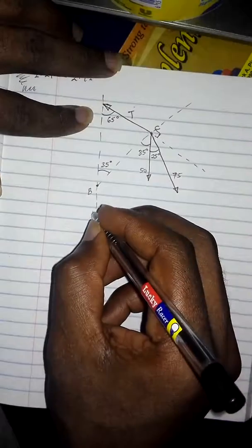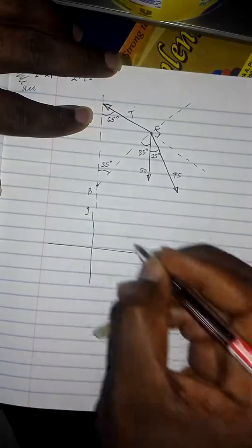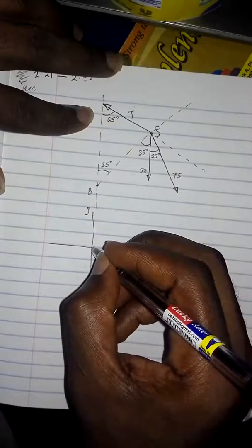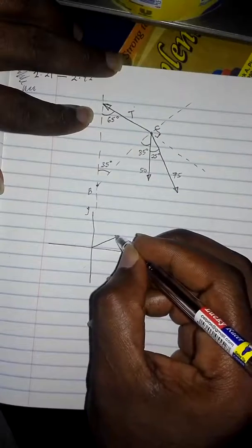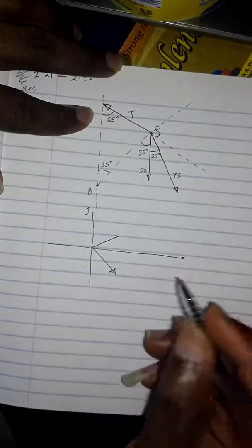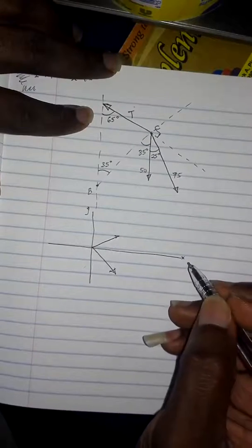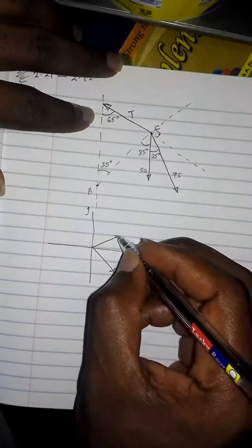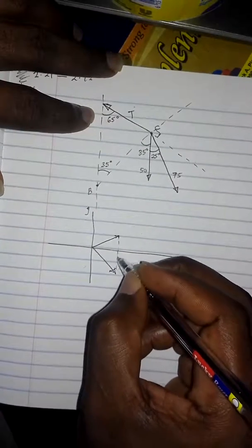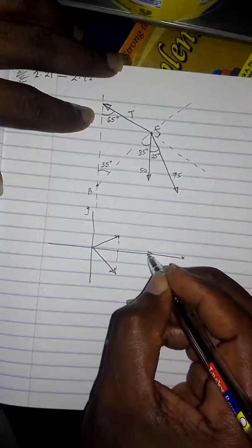What we're trying to say is this: if you have, for instance, these as your usual x and y axes, and you have some force combinations, you have a force directed this way, you have another one directed this way, such that the resultant at the end of the day points in this direction. It means that when you get the component of this force to this direction and the component of this force to this direction, and you sum them, their sum is going to give you exactly that resultant, which is along this direction.